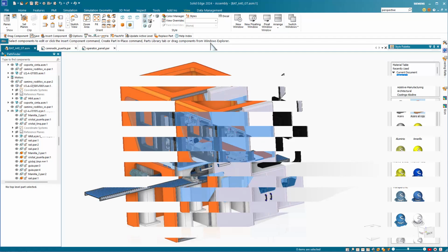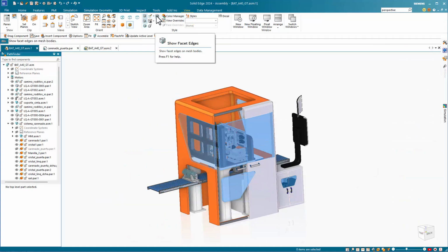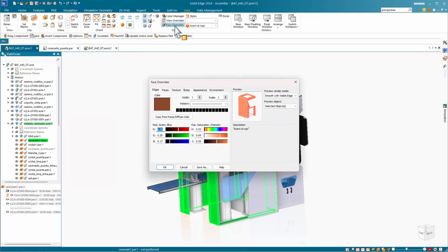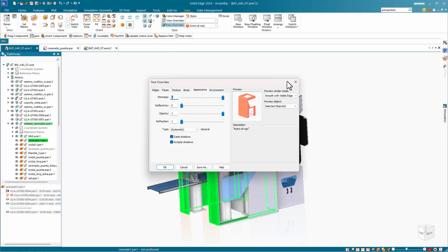It's very easy. It makes it easy and quick to change colors and helps you visualize the model and even prepare for rendering. Additional visualization tools can be had on the View tab, and these will include high-quality rendering to help smooth out some of the edges, perspective to get a better view of your models, sharpen, single-color edges, floor shadows, and floor reflections to get a more realistic visualization. Face overrides will allow you to change individual face textures and visual properties.